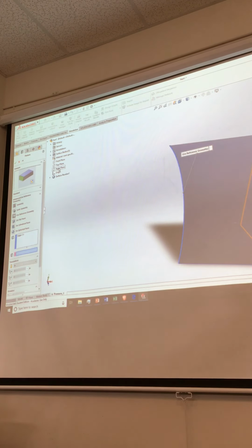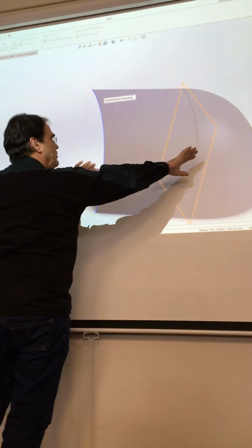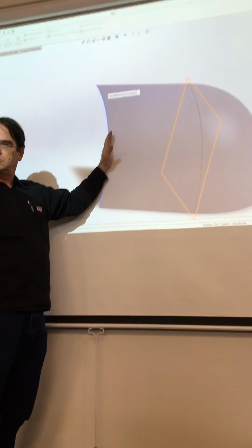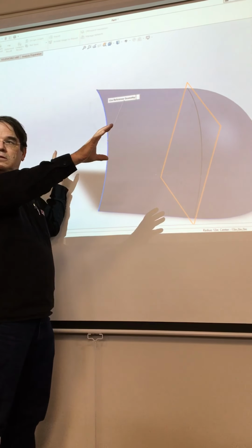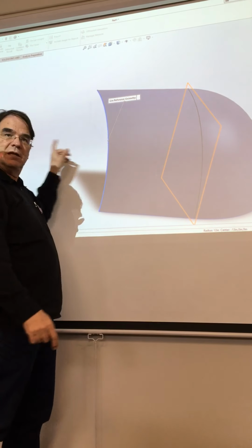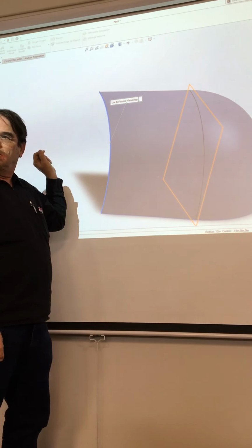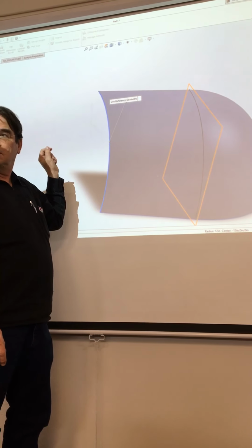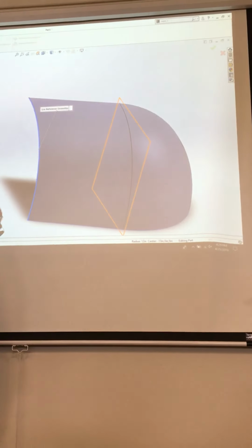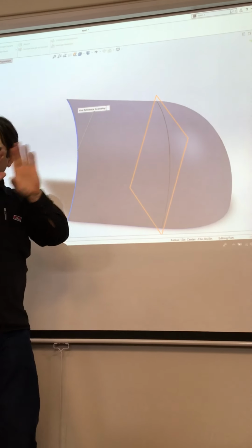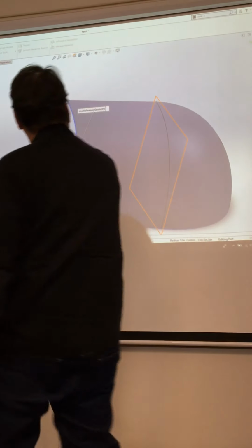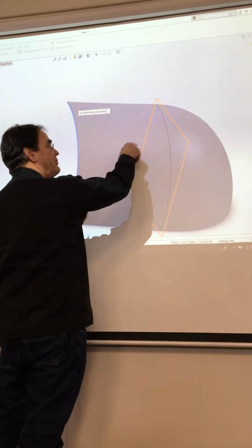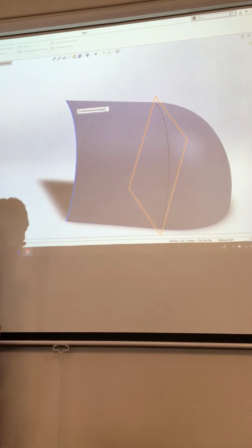Okay, so if I pick the right plane here, now what does symmetrical mean? It can't move that way, it can't move this way, it's going to stay in this location, right? I'm going to fix this location so it can't move either way. Because as it grows, what's it going to do? Well, the amount that side grows and the amount that side grows over there are going to be equal because it's symmetrical. Right, so I can fix this. When we have symmetry, the perpendicular planes of symmetry don't remain perpendicular, right? So if I'm going to fix this part here, I'm going to use this plane as my reference plane such that I can fix the perpendicular one.